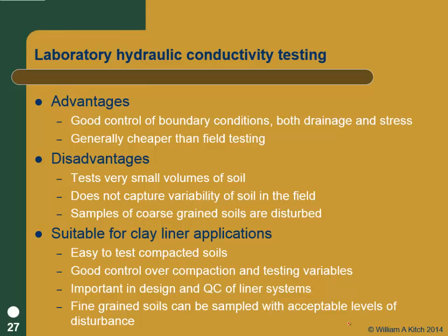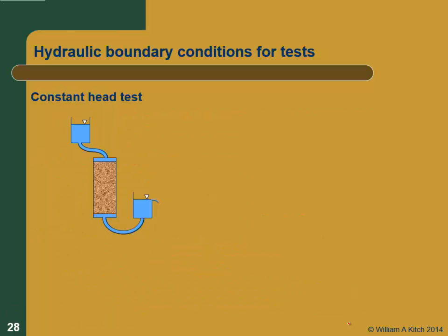They're not such great techniques for figuring out how well the water is going to be flowing out of a well or across some place. You're better off in those cases actually doing pump tests in the field to get a global hydraulic conductivity for the field. All right, so let's talk about these.